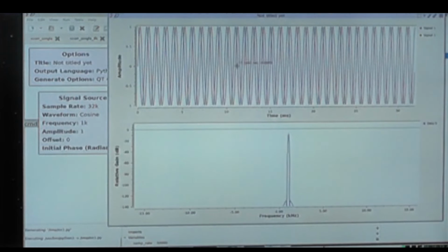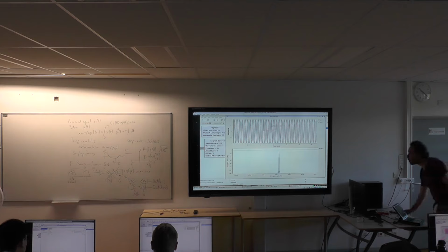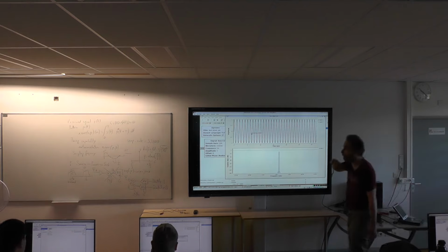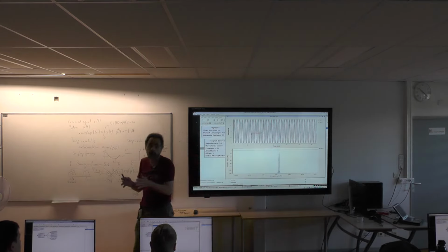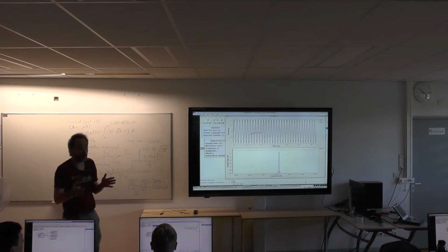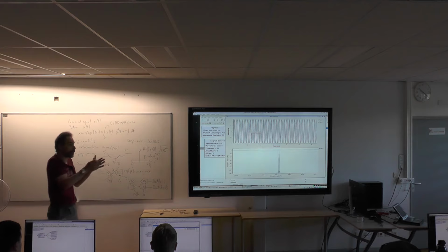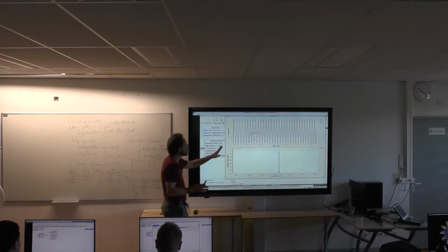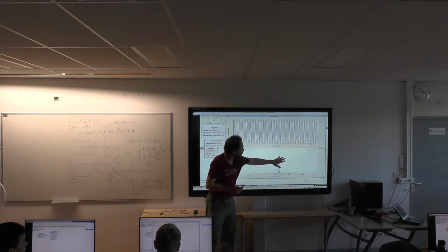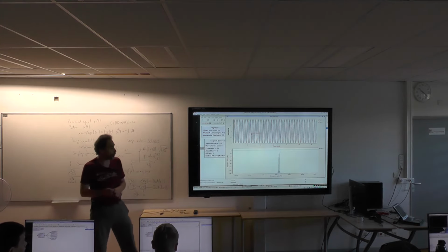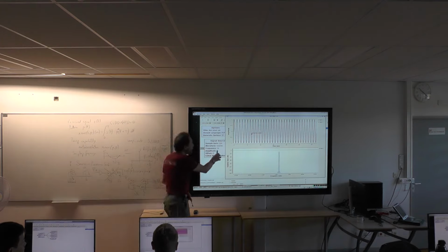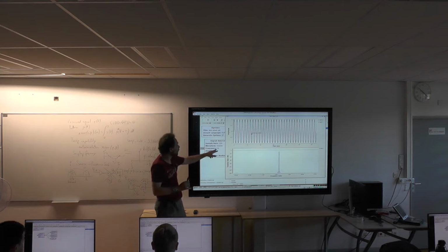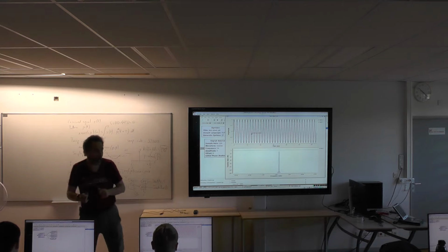And when you're executing this flowchart, you see here what it looks like. So we've got on top the time domain, and we understand now that there are two quantities because you've got I and Q. Never tell an engineer that you measured an imaginary voltage. Imaginary voltage is a real quantity shifted by 90 degrees, so you've got two voltages, I and Q. And in the frequency domain, you have a unique spectral component which is shifted by the 1 kilohertz. GNU Radio writes 1K, but when you enter the value, it's a Python expression, so you must write 1000.